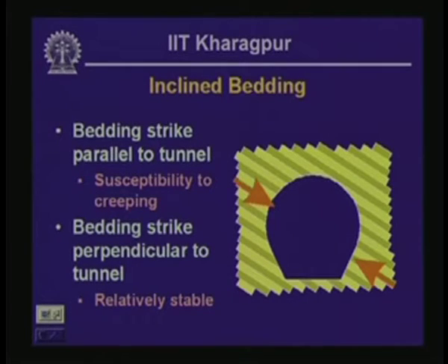And this is particularly the case for tunnels constructed through ductile rock, and what you are going to end up with is a situation like this. So, here you can see that the portion which is to the top left of the tunnel alignment, we are again looking at the cross section of the tunnel, is closing into the tunnel, and this kind of a problem is called closure.